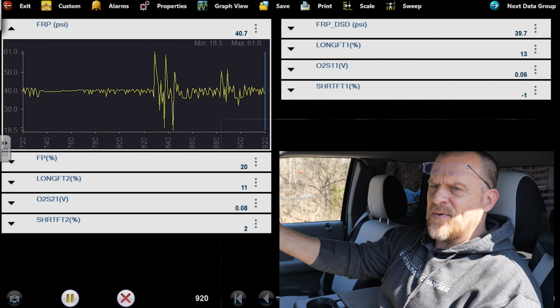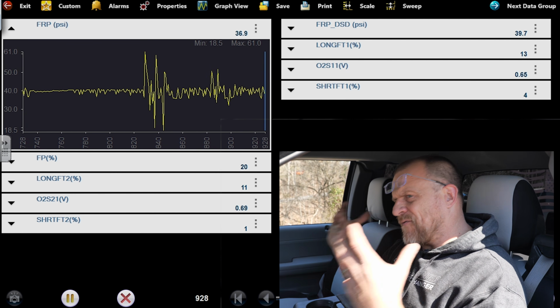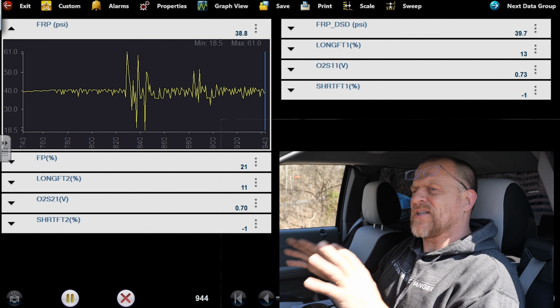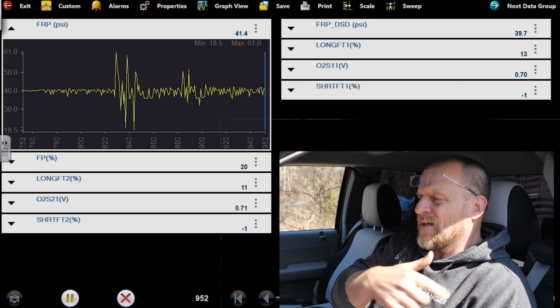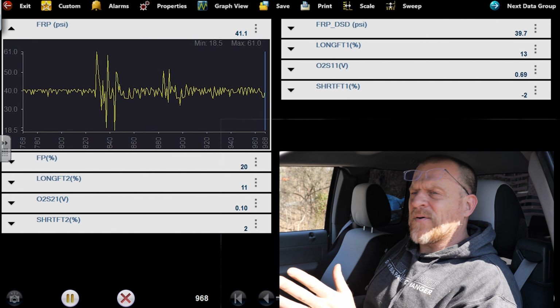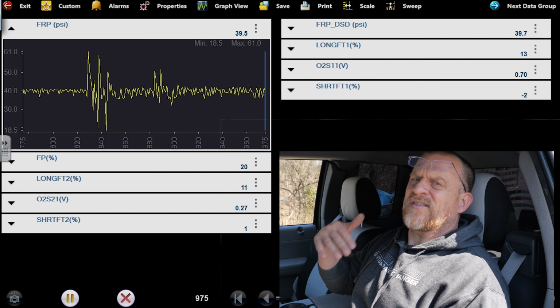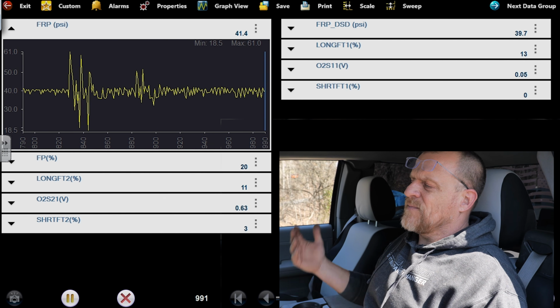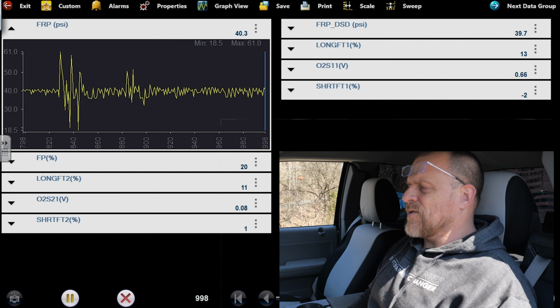That's why we test drove it, because I can then hold it for a longer period of time at that high RPM when we have that fuel demand, kind of like what I'm doing here when I'm snapping the throttle. We're increasing fuel demand on that pump because our injectors are spraying. But that momentary drop is not a problem. It's the sustained demand. As long as it can keep up, then you're good, and we were able to on the road.